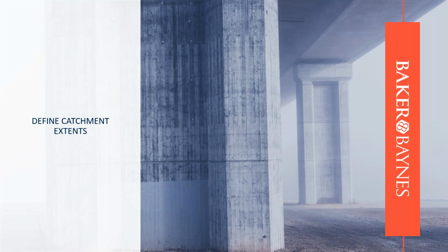Okay, now let's look at another part that's normally done on Google Earth. What consultants normally used to do in civil engineering is find the site on Google Earth, put a pin, and then use a polyline, increase the thickness, and just draw what you would feel is the contributor area or the catchment. It did work to a certain extent. I'm not going to shoot it down totally, but it wasn't as intelligent. Definitely not. It led to most designs being very conservative. Conservative is fine, especially with water, but if you've been super conservative, it affects the costing, it affects everything.